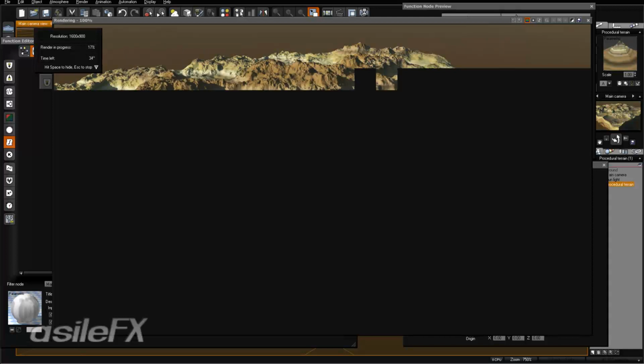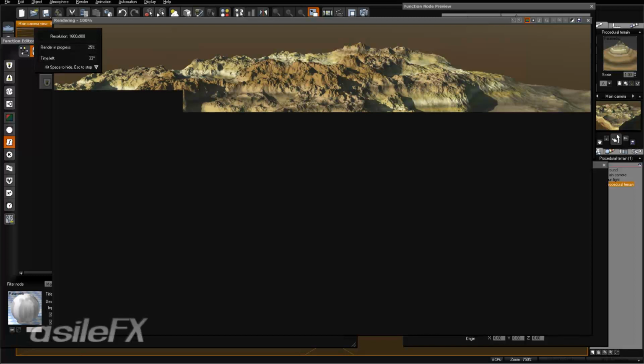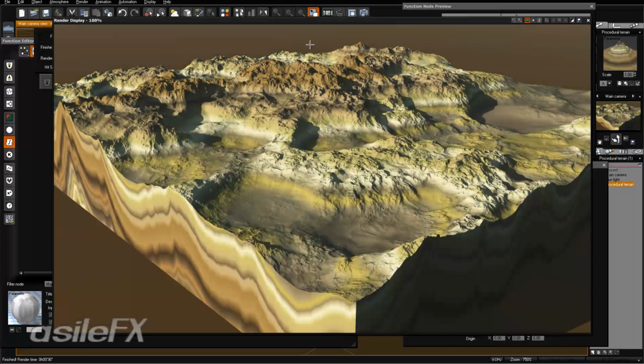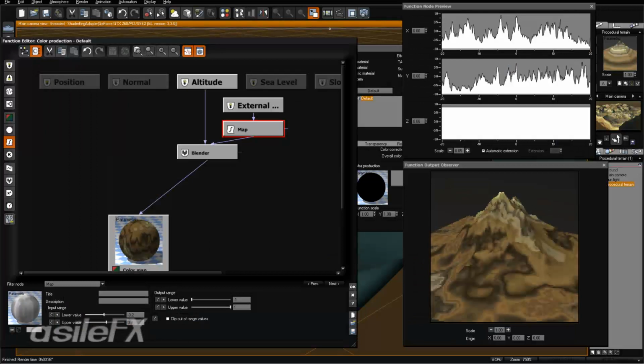So if I did bring this down to 0.5, let's just take a look, because it's going to intensify the output a lot more, so our subtraction becomes even higher. We can see a lot different of an output. So now the subtraction is very extreme, and the layers are starting from much lower within the terrain. So you could use that as a starting point and then just adjust the ratio in order to flatten it out or get it to conform a little bit more. I'm going to bring that back up to 0.9, and we're going to work within the -1 to 1 range.